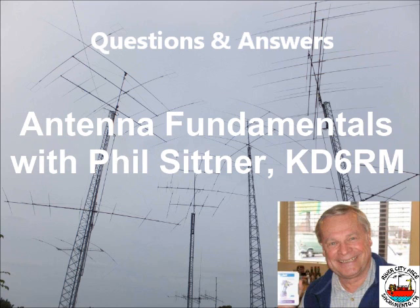At the antenna. That way you don't have these feed line losses. Some of the energy used to perform the match is absorbed by those elements doing the match. It could be a coaxial stub, it could be an LC network, it could be a gamma match, and there's a beta match.